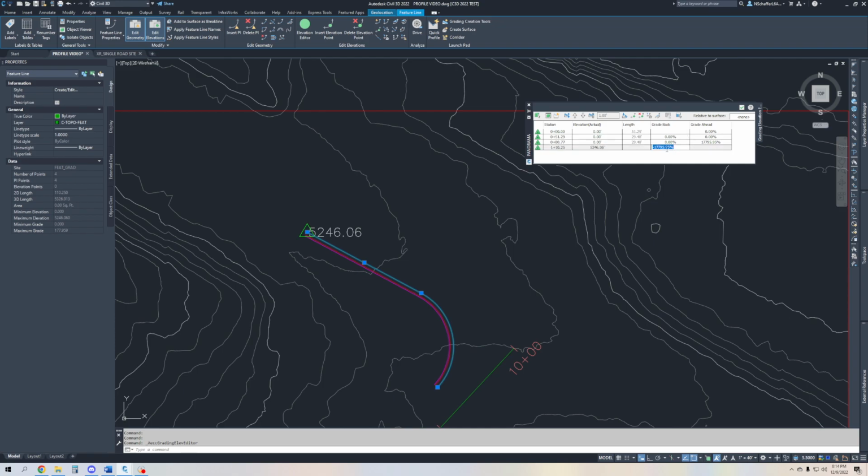And let's say I want it to be a negative 1.5% slope. So I'll type in negative 1.5, hit enter, and now you can see that this elevation here is now assigned. So adding a percent slope here changes the elevation of the next point when you do grade back in this case, or if it's reversed, it'll be grade ahead.